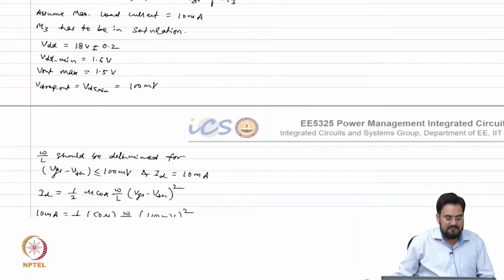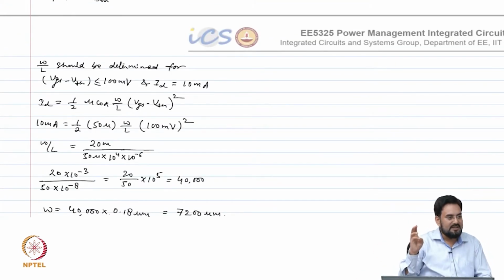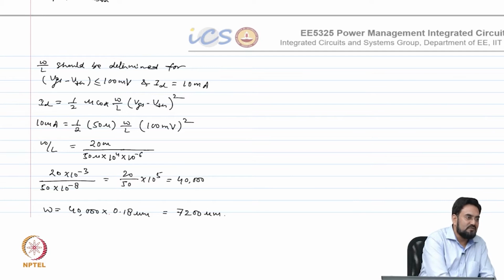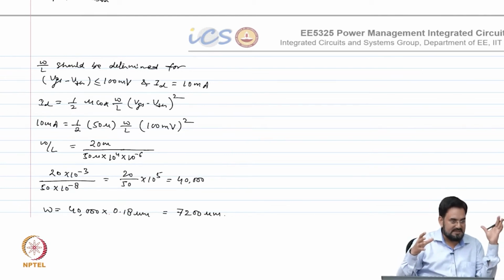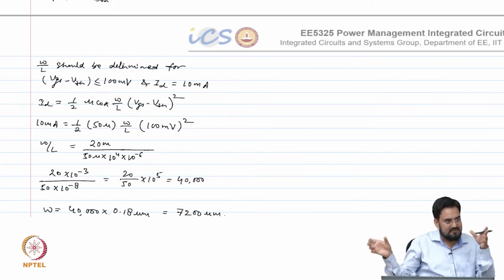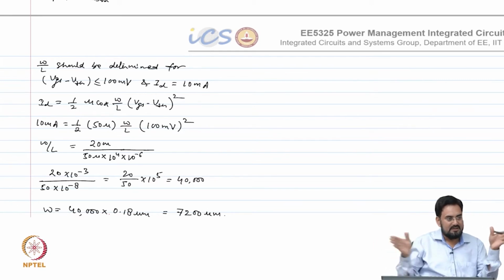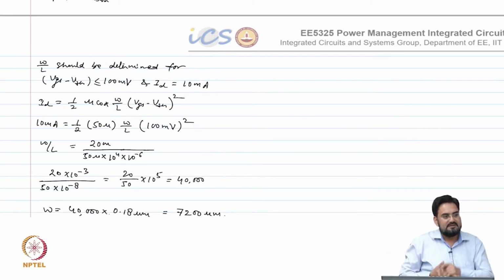And if you are designing for a fixed load, what will be the worst case? The worst case will be the mid range cap, of the order of nanofarad, where both poles, the omega P2, which is the fixed pole, and the variable pole, which is the output pole depending on the output cap, both fall within your UGB.